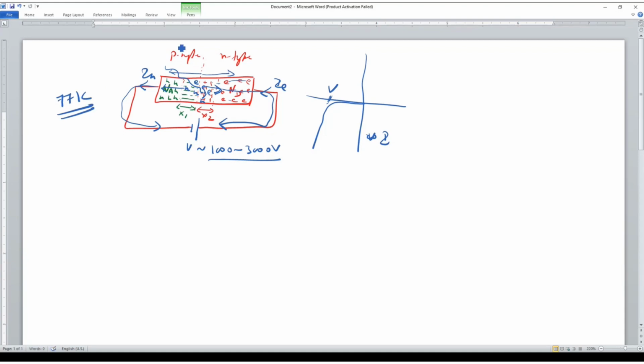At this temperature you have very less number of minority charge carriers, so you don't have any avalanche kind of condition. Obviously silicon में हो सकता है, but germanium में और decrease हो जाता है. तो germanium is more used as a solid state detector for radiation rather than silicon, but you have to maintain this kind of temperature. So when you maintain this kind of temperature, your depletion region increases, and when the region